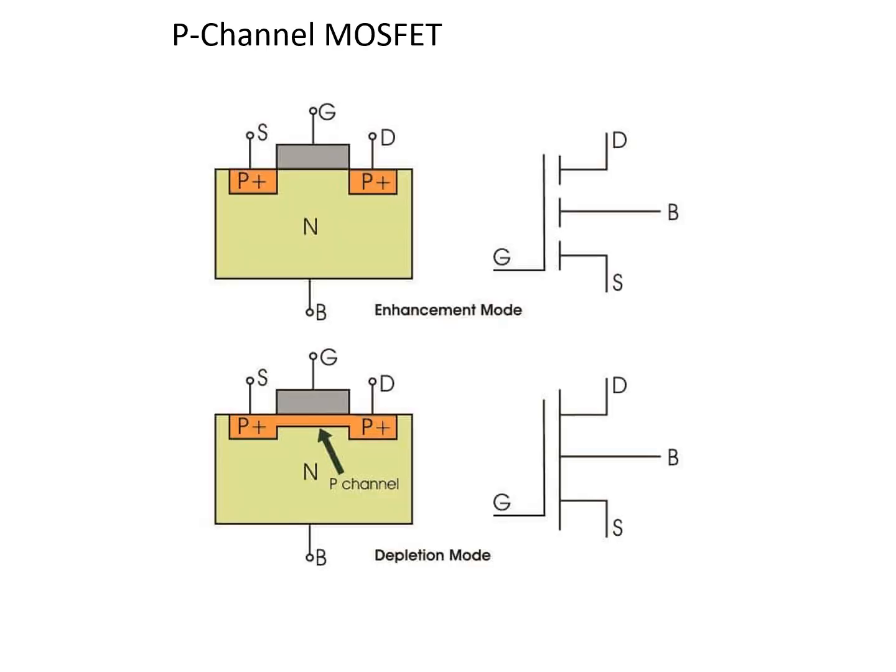P-channel MOSFET. Now in P-channel MOSFET, the drain and the source are heavily doped with P region and the substrate is N-type. The current flows due to the flow of positively charged holes, and that's why it's known as P-channel MOSFET. When we apply the negative gate voltage, the electrons present beneath the oxide layer experience repulsive force and are pushed downwards into the substrate. The depletion region is populated by bound positive charges which are associated with the donor atoms.